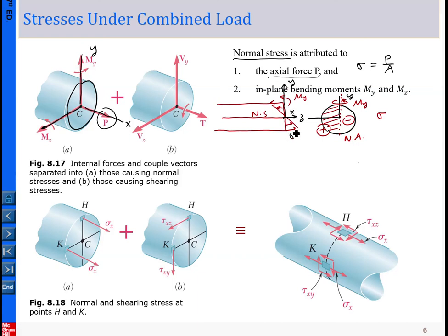So basically the bending stress in terms of our coordinate system defined here is sigma x. Okay, and here is a sigma x as well. Now the magnitude equals My over I, that is our template, and M is the bending given in y component. And what is y? y is the distance from any point. For example, if you want to find out the stress at the point here, then this is the distance y you are going to plug in here, and I is the moment of inertia of the entire cross section with respect to the neutral axis.